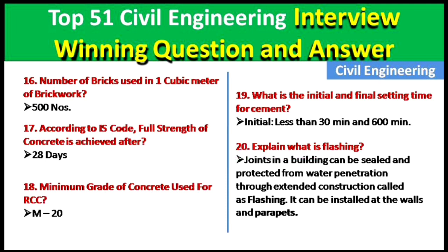Now point number 20 is explain what is flashing. Okay guys, this is a very important term and it is generally asked in the interview or job examination. Okay, so flashing is the sealing of joints in a building to protect them from water penetration through extended construction, called flashing. It can be installed at the wall and parapets.